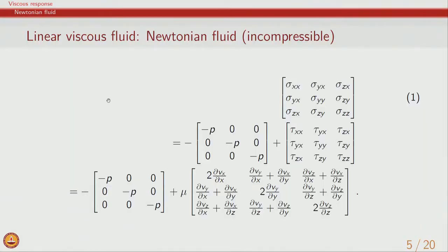And the mathematical model, the constitutive model which captures this for a class of fluids, is called the Newtonian fluid, which we are very familiar with, in which case the total stress tensor is the pressure plus the deviatoric stress tensor, and it is the deviatoric stress which is related to the velocity gradients as we discussed earlier, and the proportionality constant is viscosity.